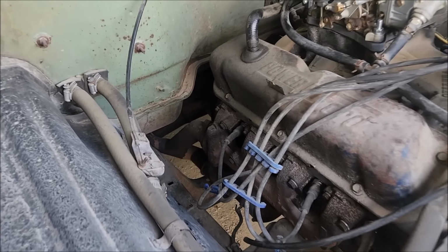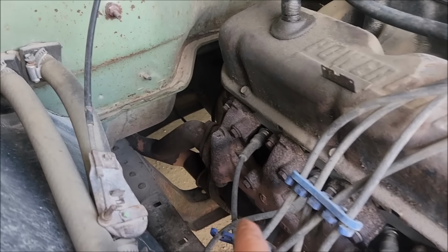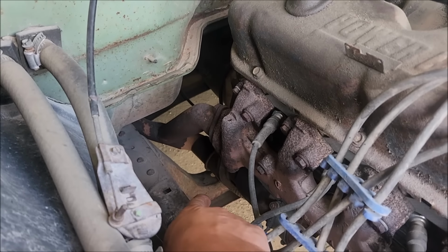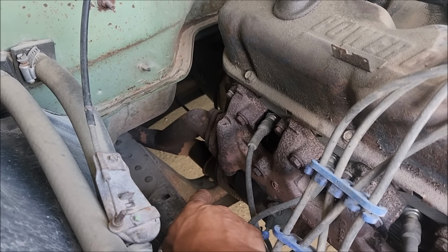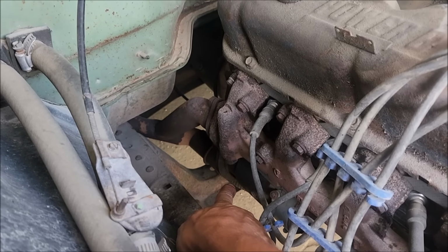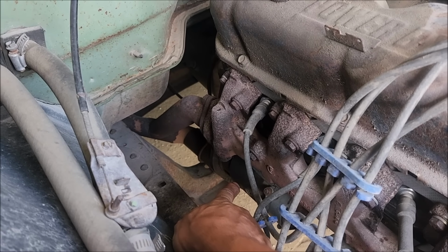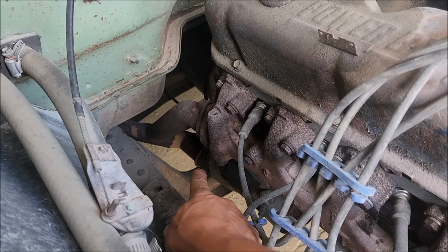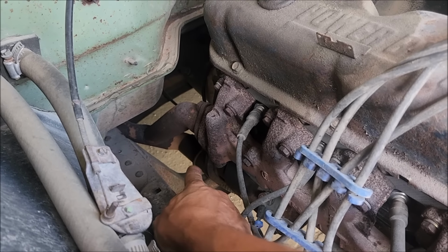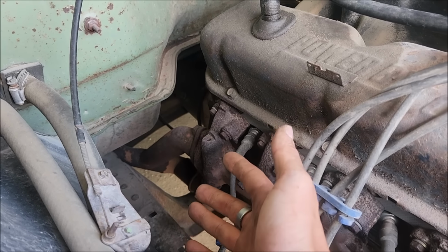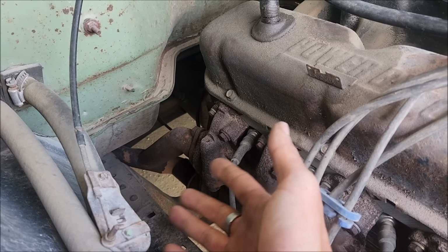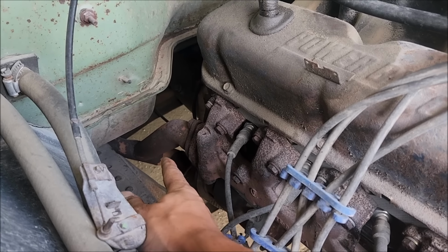Now this truck is going to be a curious install that touches on a lot of good points here. If you look down here, this goes into a Y pipe. These are the stock manifolds naturally, and you can see right down here, this is a piece of flex pipe. So there's a good chance that there's leaks, and we definitely don't want to install our wideband downstream of any exhaust leaks, because that'll give us a faulty reading, same as you would have on a fuel injected car.